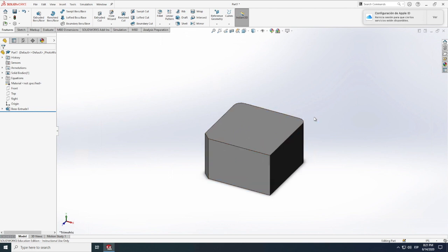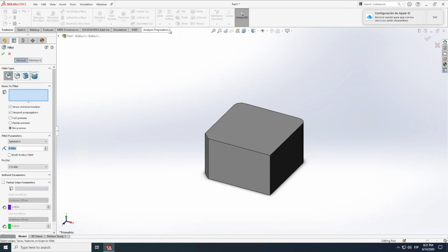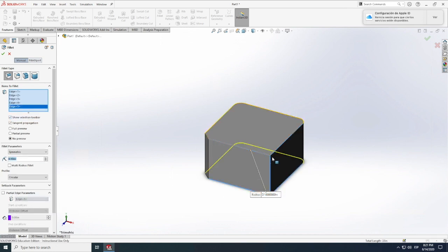Looks pretty awesome, right? But now here's where things begin to get way more interesting. You've got to remember that fillet where we did it in there. You can also do the following thing. You also have chamfer if you wanted to, but I'll just stay with fillet. So let's say I want to fillet that edge over there. I'm going to choose these 5 edges. I just kept on clicking those, and they show up over there. And then here we go, full preview. That shows us how that's going to look.